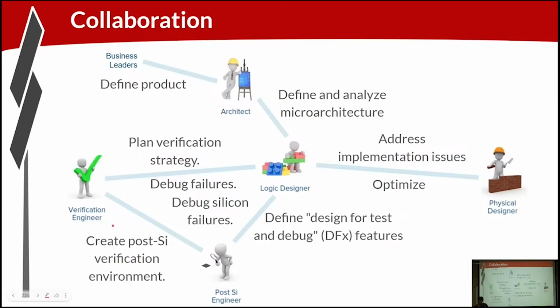Verification engineers and post-silicon engineers also work closely together on the environments, to make sure they have a post-silicon environment in place for verifying the physical silicon and leveraging as much as possible from the pre-silicon work. Test content that's written pre-silicon, we want to be portable so that you can run it post-silicon as well.